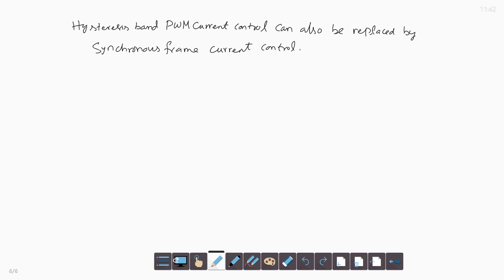Most important, below the rated speed the flux is constant at the rated value, giving constant torque operation. For speeds above rated speed, field weakening control is done in constant power mode with closed loop flux control. So, with this we will go to current control.